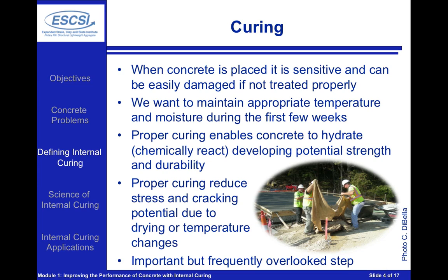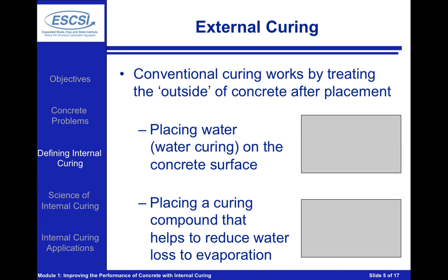In addition, curing is important because it's going to help us to reduce any stresses that develop if our concrete starts to dry and it wants to shrink and crack. So proper curing is going to be helpful while our concrete is very young to reduce the potential for cracking due to moisture or temperature changes. Now, while we all know that curing is very important, unfortunately in practice we frequently see curing being overlooked as one of the vital steps to ensuring our concrete will have a long service life.